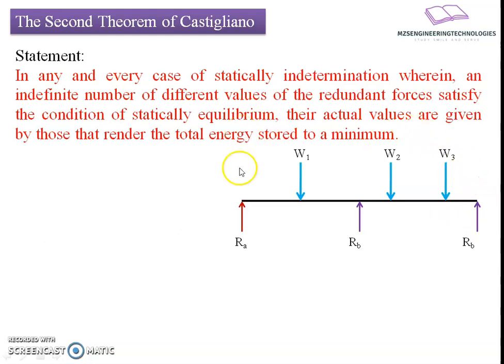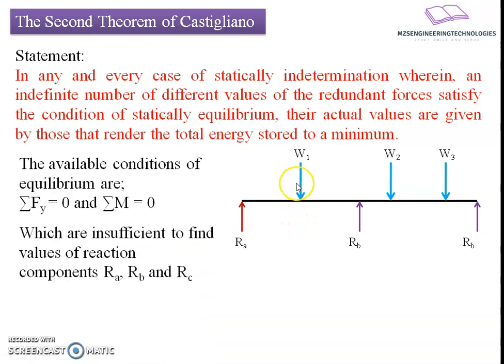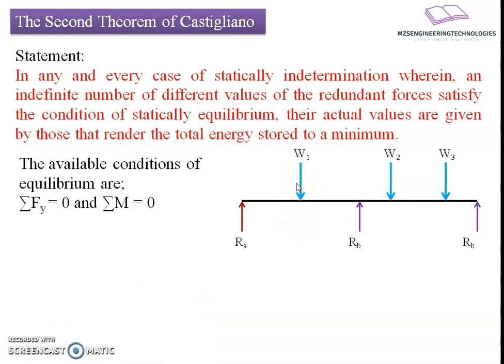If you see the force system here, it is a coplanar parallel force system, and the usable equilibrium equations for this coplanar force system are only 2. Means summation of forces in the y direction and summation of moments at any point will be equal to 0. If I use these two equations, it's not possible for me to find the three reactive forces RA, RB, and RC here.